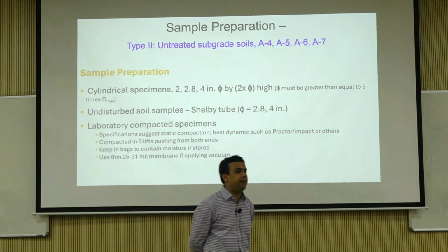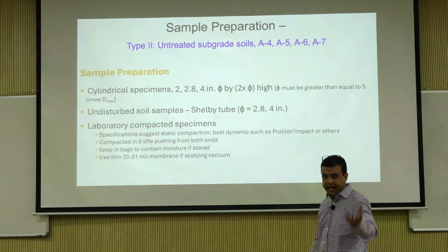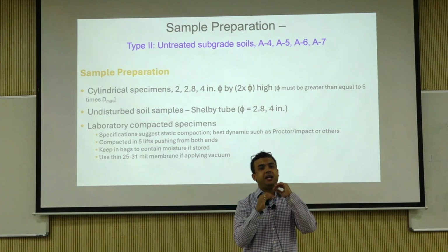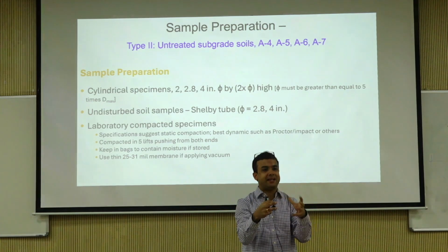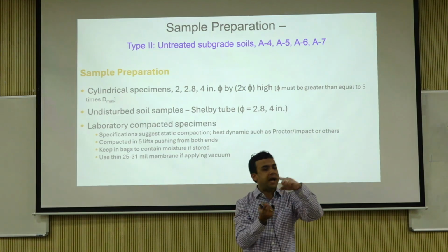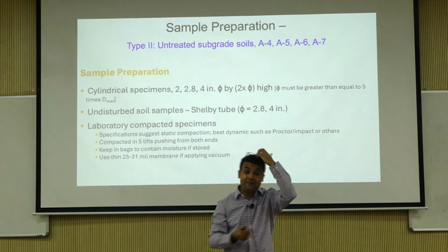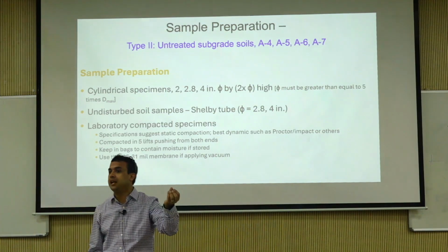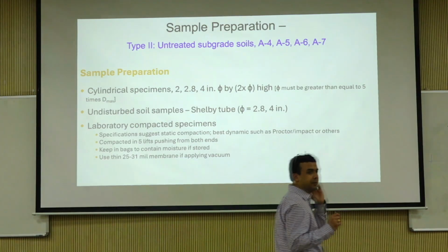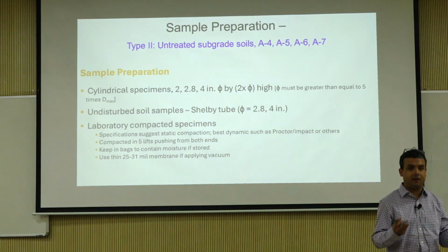Okay. So there are different ways. For example, the way I used to run it is I would calculate the target density. I know the volume of the material, and then I would say I'm going to compact in 5 layers. So I know the mass for every layer, and I know a target height of every layer. I do not stop compacting until I meet that. Now the question is, do you have a soft aggregate? If you have limestone and stuff, your aggregate may crush. Excessive compaction may crush your aggregates. That's one problem, right? Mine, that was not a problem. I always had, so I just meet it. So it's difficult. That's what I'm saying.